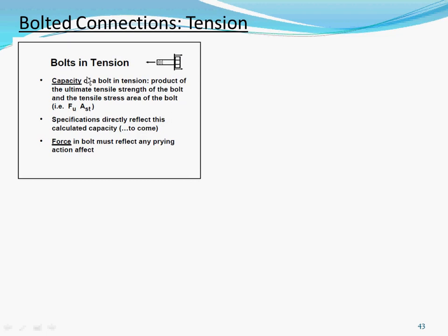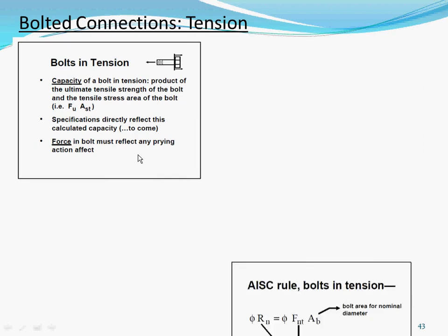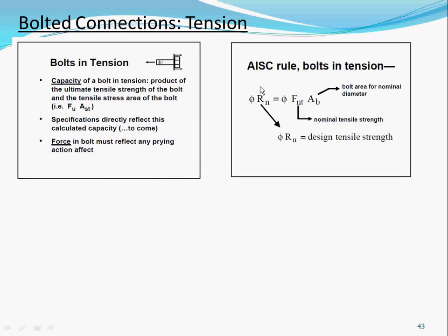Bolts in tension, the capacity is very easy, it's just Fu times AST. However, your forces are compared to it, and you must consider your prying action. So I'll get into prying action later.